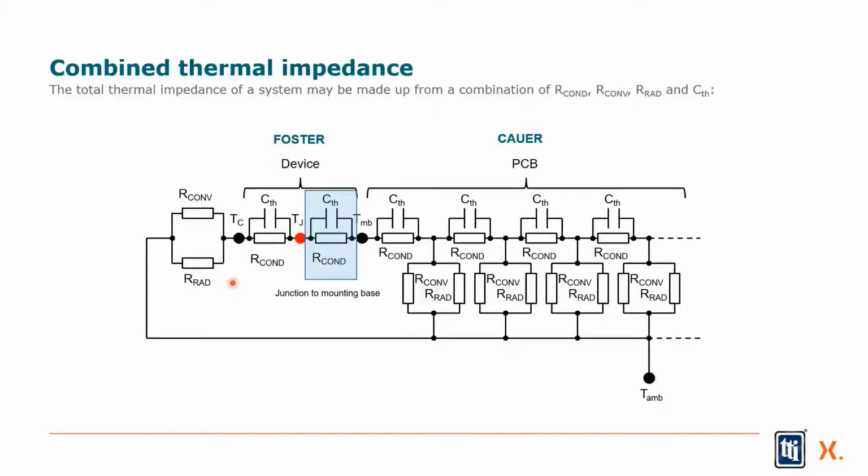So I can take a part that Nexperia builds, one of our MOSFET devices, and I can actually calculate the equivalent thermal resistance and capacitive capability of the device, the thermal capacity of the device as well too, convert those into R's and C's, run them on SPICE, and I can actually simulate the thermal with electrical equivalents that, again, we all know. So this is what it looks like.